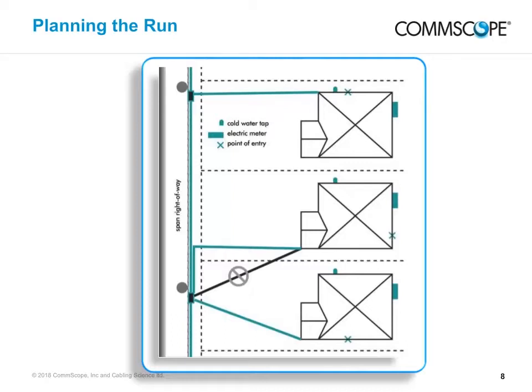A 60% braid foil shield works for almost all CATV installations. If you are installing cable intended for a more active two-way service, internet high-speed data, you should consider a tri-shielded cable. Cellular and pager towers produce radiation that tends to raise havoc with CATV channels 19, 20, and 21. Ham radio aerials may also signify a problem. Urban zones have inherently high levels of RF pollution. We recommend tri-shielded cables with a minimum of 60% braid for areas with high RF concentrations.